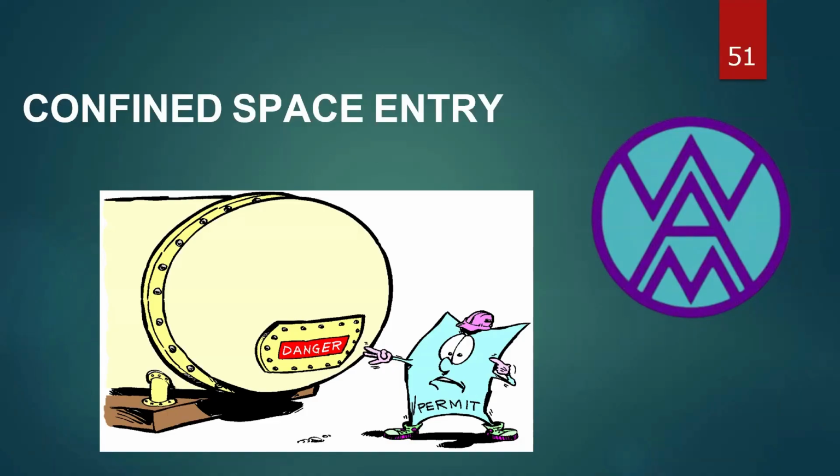What will they do? They will first check what the hazards are in that area. One by one, they will check if there's any lack of oxygen, or if any limit is exceeded, if there are any toxic gases, any poor lighting, or any hazard of engulfing, where a person can be engulfed by some material. So that is basically permission.